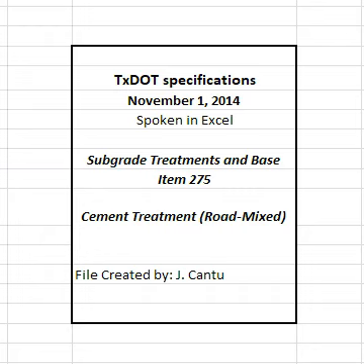4.2 Pulverization. Pulverize or scarify existing material after shaping so that 100% passes a 2.5 inch sieve. If the material cannot be uniformly processed to the required depth in a single pass, excavate and windrow the material to expose a secondary grade to achieve processing to plan depth.